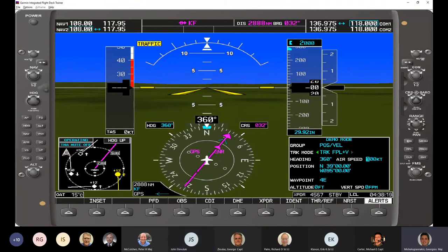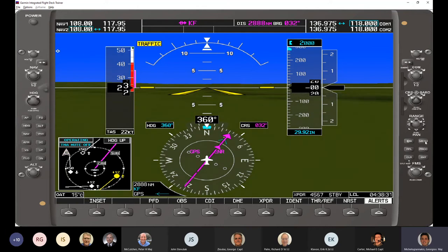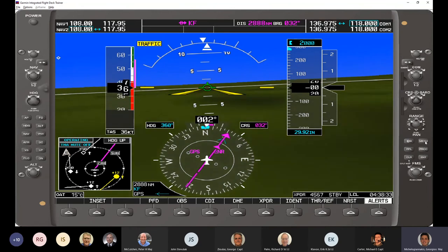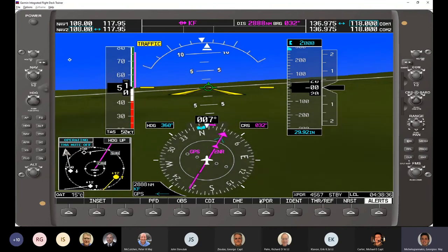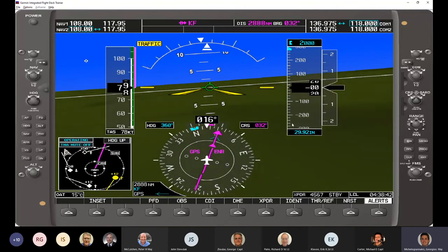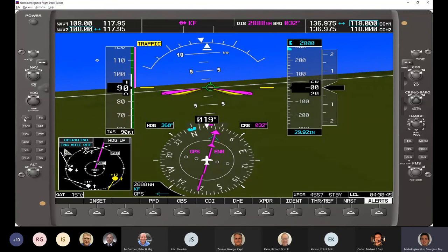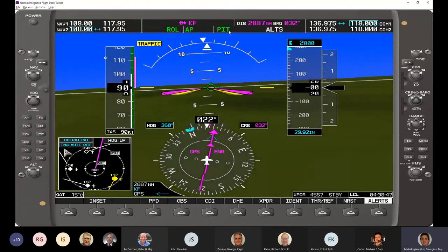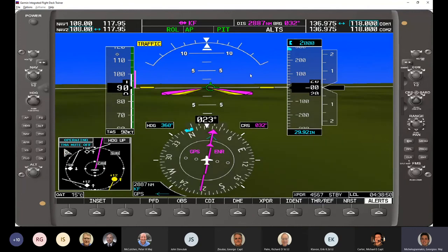Do you want to go to 100 knots today? Let's see. Okay, this 90, sure, why not? So we're going to go at 90 knots, and right now we're trimming the trees because we're on the ground. But that's fine for now. The first thing I want to do is climb. I feel pretty motivated to climb right now. So when I press the autopilot button, notice that as we said, we're going to go to roll and pitch. The autopilot is on. I know that because it's here. The altitude select mode is armed, and it will become active when our altitude becomes equal to the altitude bug.